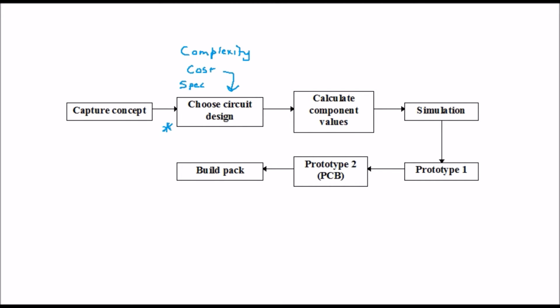Two important points to bear in mind when choosing a circuit are that simple, elegant designs are often more reliable than complex ones, and this might be especially important in applications where access to the system is difficult. Secondly, the choice to use specialist components only made by a single manufacturer may cause problems in the future if these components are discontinued by that manufacturer, so sometimes it's better to use generic components.